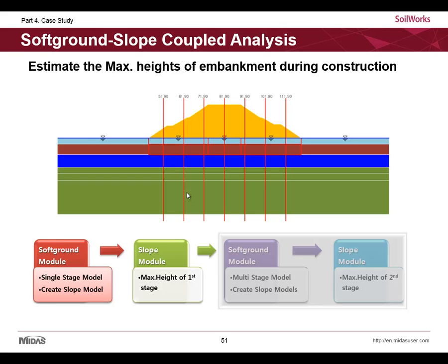So multi-stage loading allows the strength to increase as consolidation proceeds, but the rate of filling must be limited so that the load ratio is within the acceptable factor of safety. In this case, an iterative process is required.